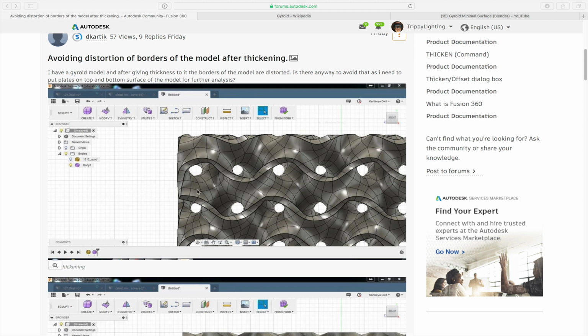So in this little tutorial, I want to go over why I use Blender in conjunction with Fusion 360 and why that's such a powerful combination. In Fusion 360, you can create solid bodies from T-Splines, which you can create from a quad mesh. But the abilities to create complicated meshes are very limited in Fusion 360. On the other hand, in Blender, you can create really complex quad meshes like this gyroid here. But you can't create solid bodies that you just add mechanical features to. So that makes that a great combination.